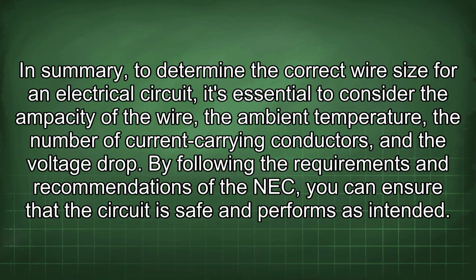In summary, to determine the correct wire size for an electrical circuit, it is essential to consider the ampacity of the wire, the ambient temperature, the number of current-carrying conductors, and the voltage drop. By following the requirements and recommendations of the NEC, you can ensure that the circuit is safe and performs as intended.